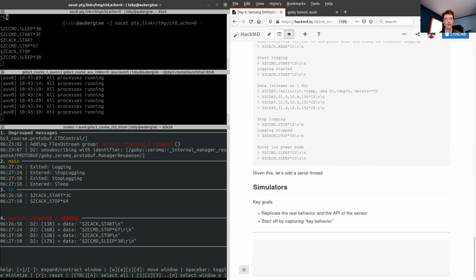If you find a bug in the real sensor's interface or a fluke in it, ideally you want to add it to your simulator, show that it breaks your driver, fix your driver, and show that it works with your new featured simulator, and then also with the real instrument. So there's an iterative process that you want to do, because that's going to give you the most bang for your buck out of your simulators.